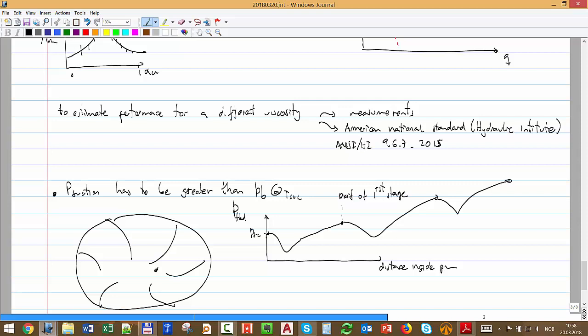But the first stage is very critical. Let's say that the P suction is exactly the bubble point pressure. If you go down, then gas bubbles are going to start coming out of solution. These gas bubbles might do very nasty things on the impeller. They might accumulate, they might block part of the impeller such that you reduce the passage. They might cause cavitation, in which the bubbles are gas, but afterwards they convert to liquid, and then they create a very strong hammering force on the wall of these blades.